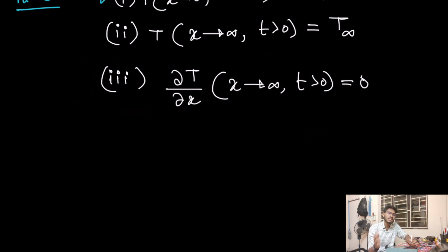But if somebody said that I am an engineer, then I need only some approximate distance at which the temperature is not equal to T infinity. If it is equal to 0.9 T infinity, I am happy enough. Then you can define something like that delta T.